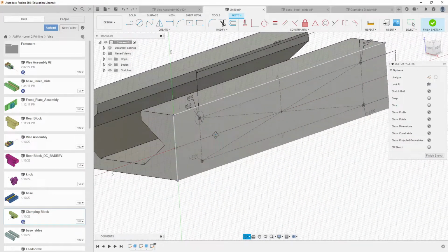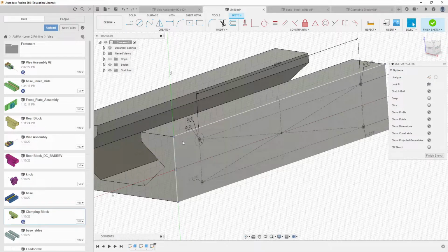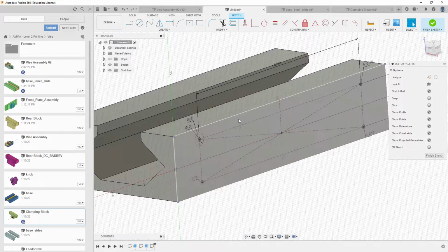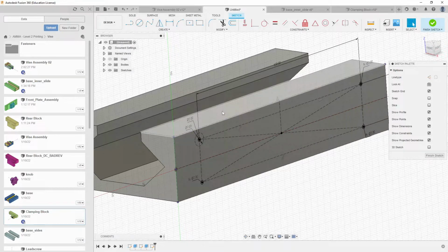And that's a little bit of a problem because this is a deep hole, and tapping the plastic is kind of messy. You're probably going to screw the threads up. You have to run it in, run it out many different times. It's deep enough that you'll have a buildup of plastic particles, so you get plastic particles all in it as you try to pull it out, which ruins your threads. But if you keep running it forward into it because it's a blind hole, the chips don't come out the other side. I guess you could make it a through hole, and maybe that would help. I don't really think so. It's just a pain.